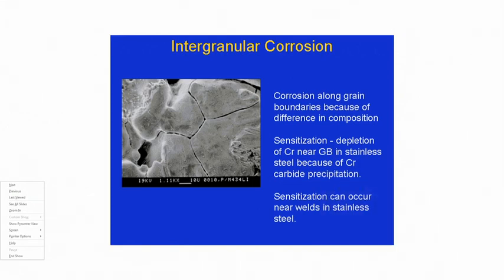That is why we see it etched when you look at the microstructure of any component. But you have to understand that in pure metal the area fraction or volume fraction of grain boundaries is a little higher than that of grains, but not so high as to affect the overall corrosion rate of the component.